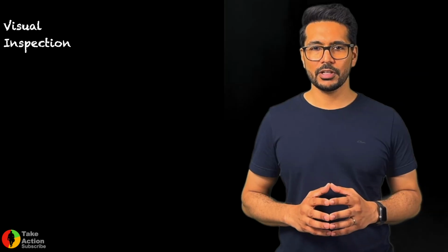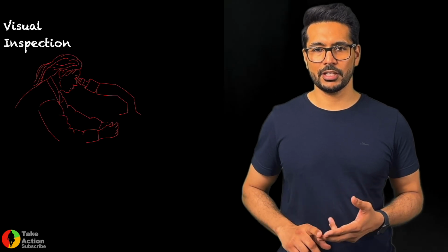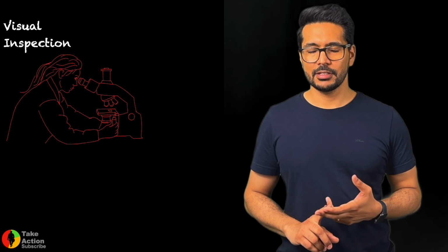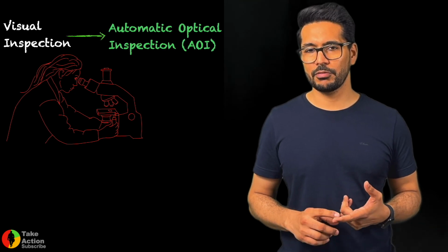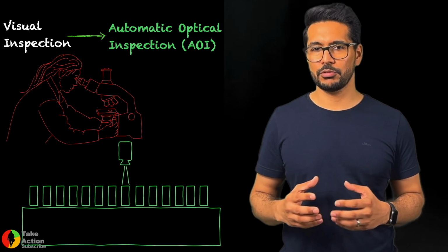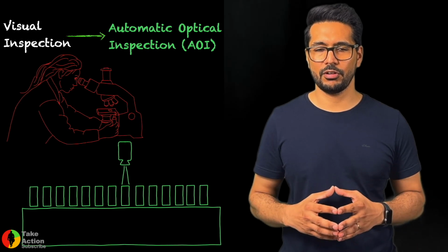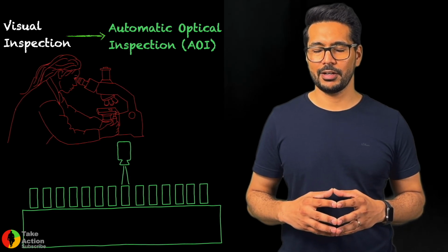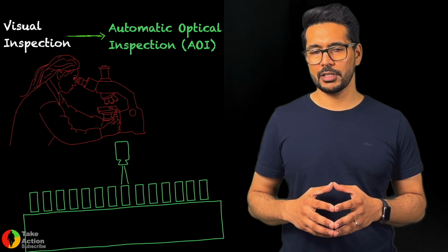Activity number 9 is another external activity which can be easily optimized. In this example, we have seen that we are going to the microscope and checking the dimensions there, which can be easily optimized. The visual inspection is mostly unreliable. We have to do MSA every year and we have to train the worker in production, and still we have a lot of manual error.